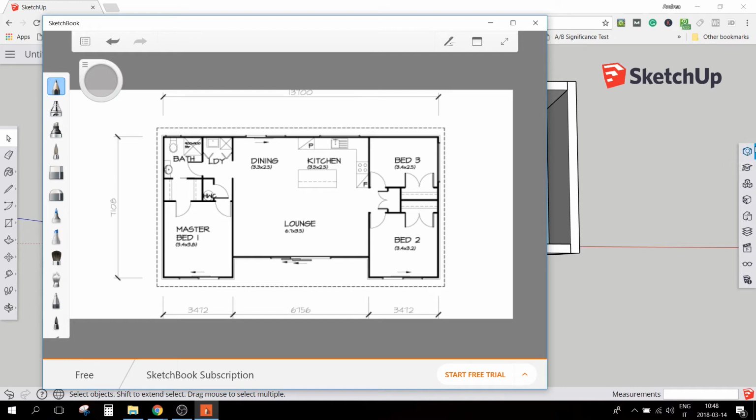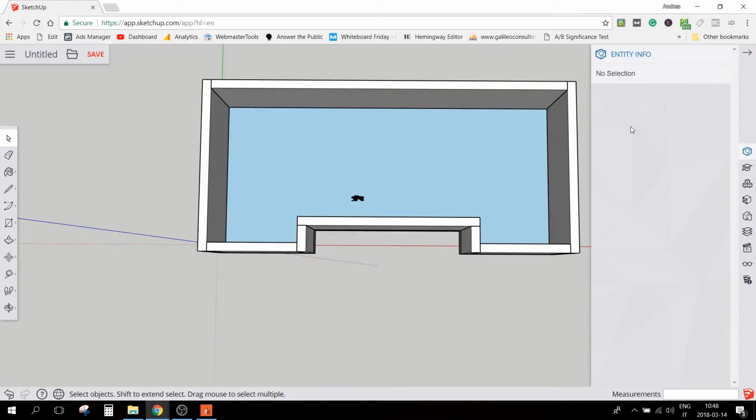So if I click on this entity info, I can select something. I can draw a measure, for example. I can simply draw a line, and for example take this point to this point here, draw a line, and then press space. I get the select tool, I select the line, and I see that this line is 14 meters and 374,